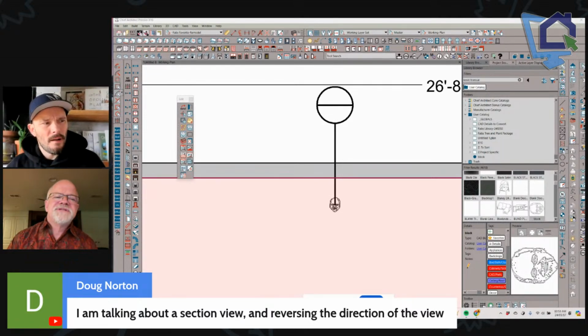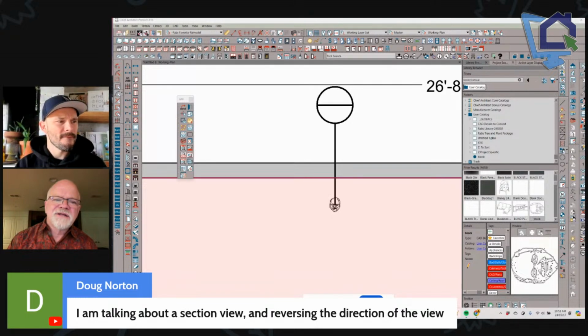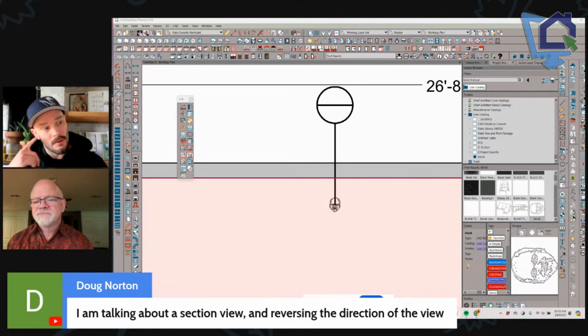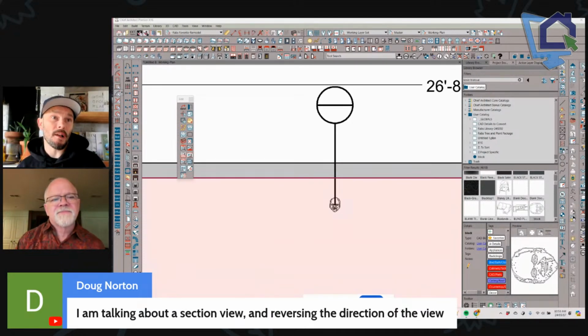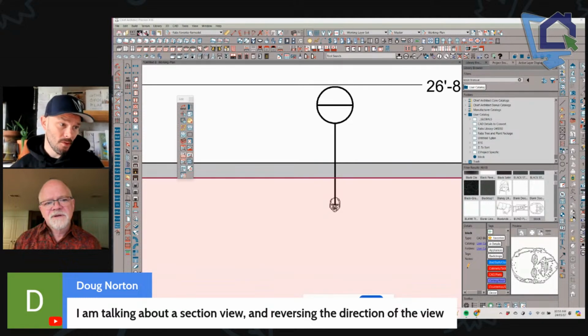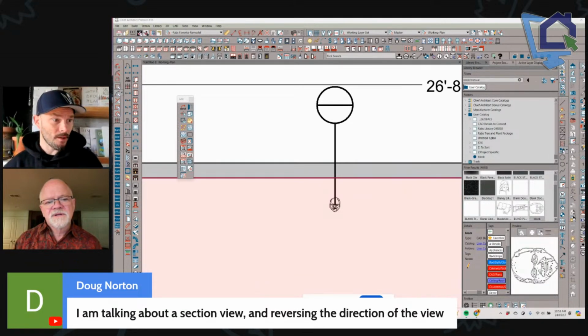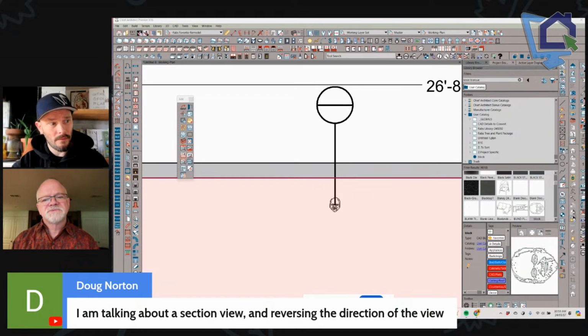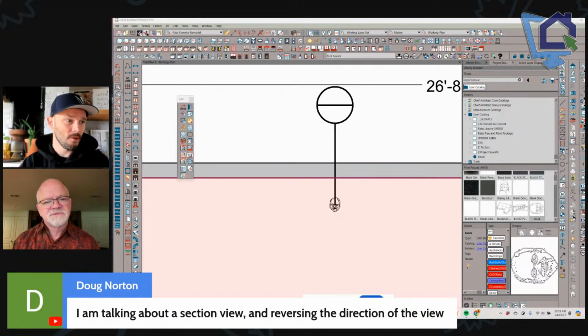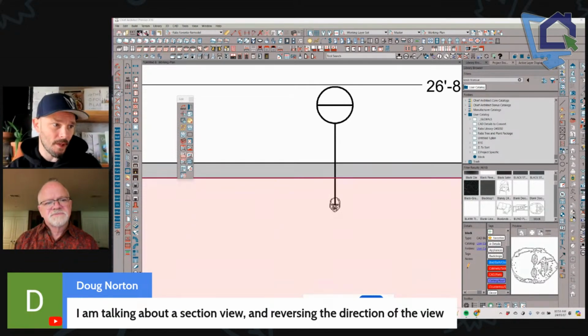And I was thinking in 16, when you drag that close to the next wall or object, it flipped the flag, but maybe no, it won't flip the direction it's going in. So you'd have to make a new view. But if you have annotated that view, all your annotations are CAD based. So you could copy all of your annotations, paste them in the new view, and then reverse those instead. And at least that's saving you a little bit of time.